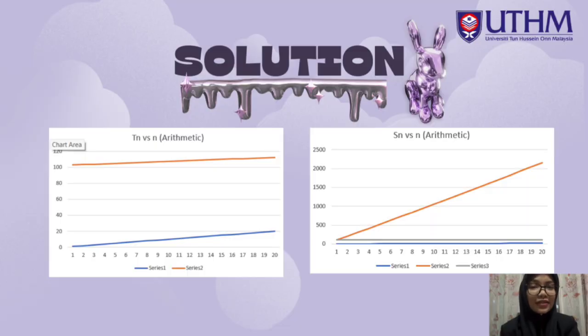After the calculation has been done using the arithmetic model, the piston rod at cycle 15 is calculated to be 110.0 mm. The piston rod reaches and exceeds the maximum safe limit at cycle 16, making it the first unsafe cycle. So, the corresponding graph displays a straight line trend, indicating steady and consistent growth throughout the operating cycles. This confirms the assumption of a constant heat effect in each cycle.